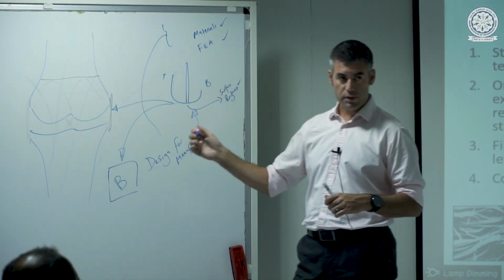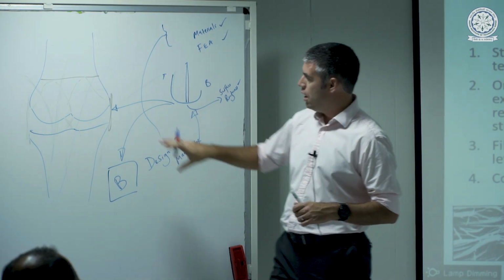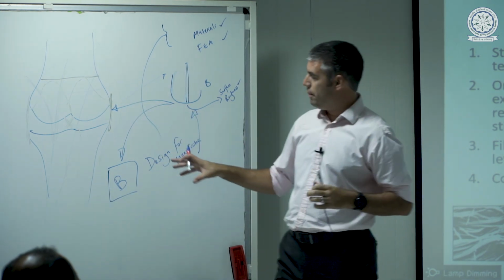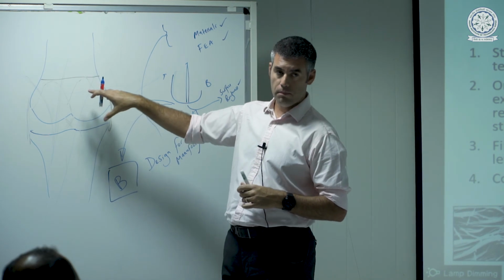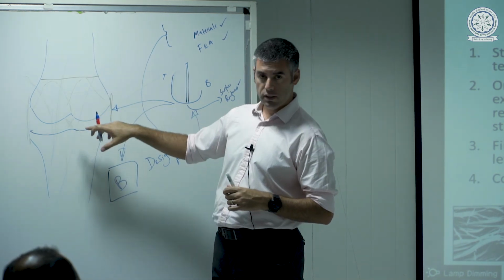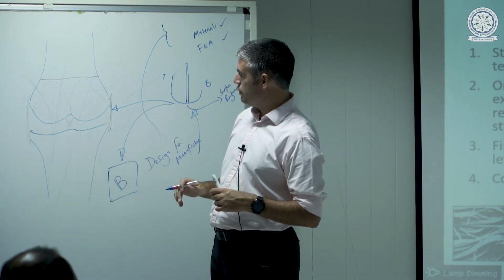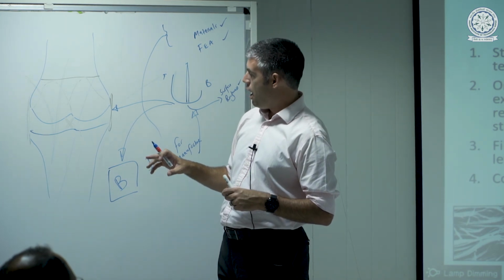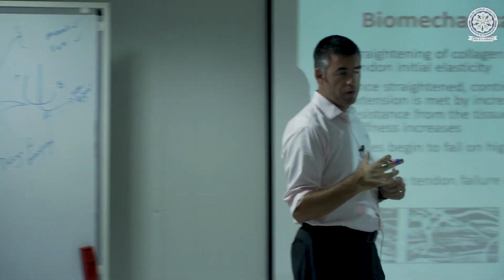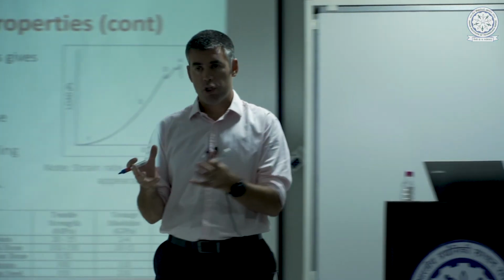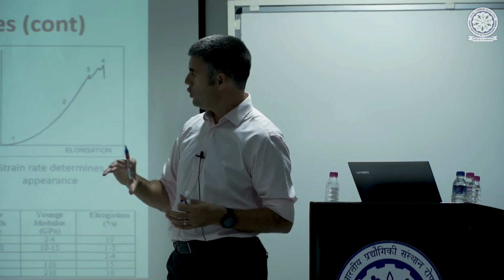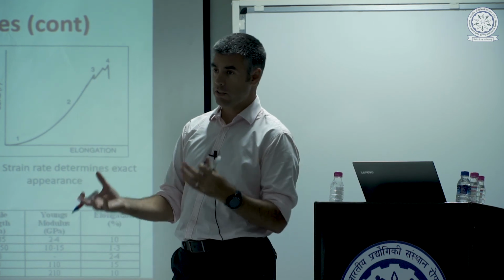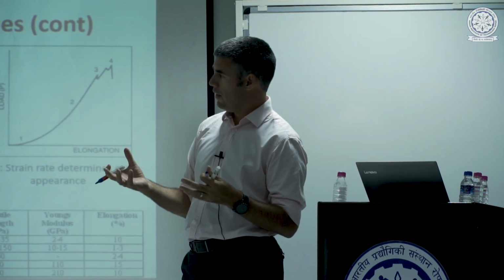So there are some implants that look at sacrificing those ligaments, so they take at least one out, and then they put their implant in. And now the question is, whilst that might make for a beneficial engineering design, does the removal of one of these ligaments, does a sacrificing ligament design have negative longer-term impacts? And that's where the field again becomes very complex, because we can take our engineering design and put it in a machine and run wear tests on a new knee or a new hip, and they can run for 1 million cycles, and you can weigh the difference between your components at the start and the finish. And so you can get some idea as to whether they are good functionally or not.